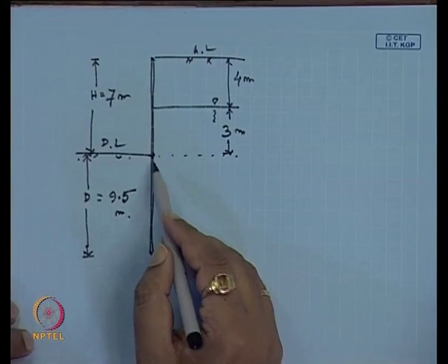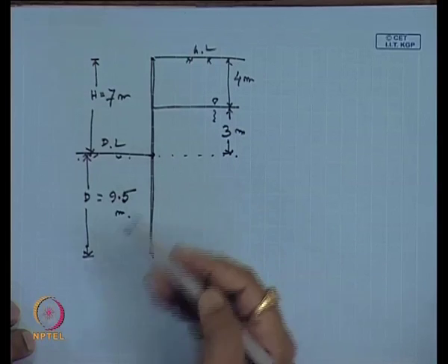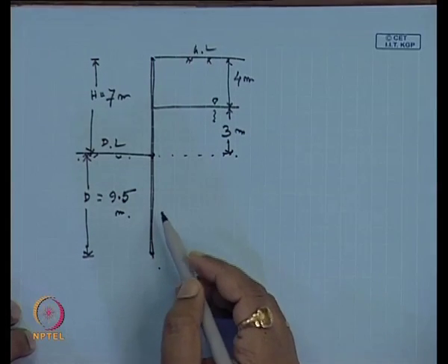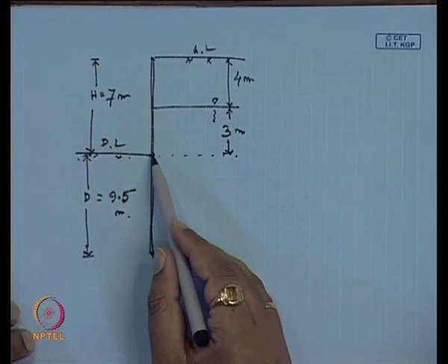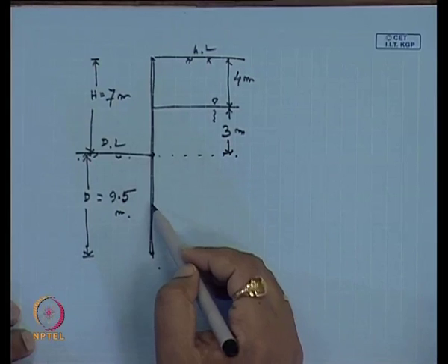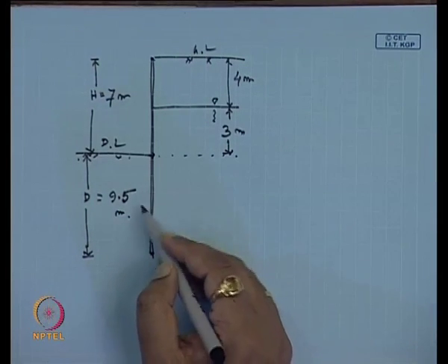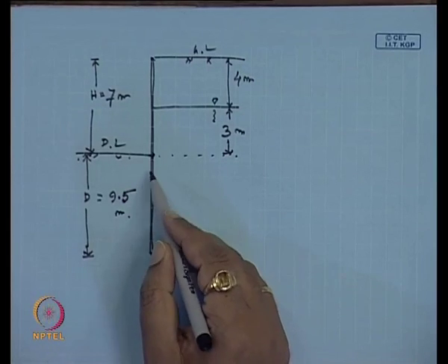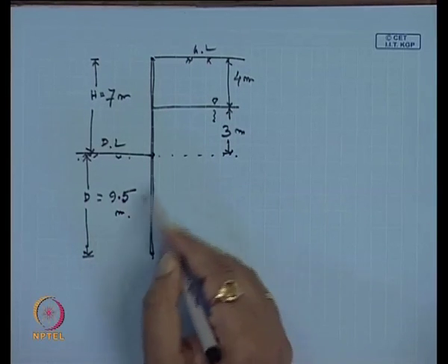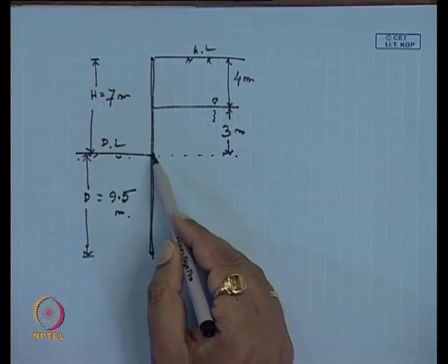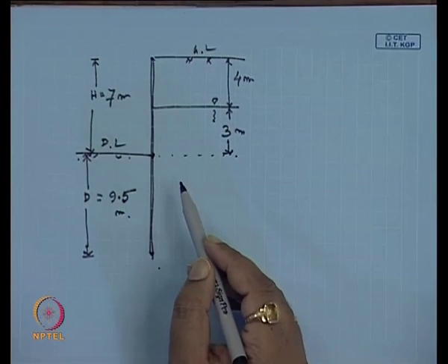One thing is that we have to go for a very high depth for this type of flexible structure. In the next section I will discuss how to design the anchored sheet pile, because sometimes this required depth is very high. All the resistance is coming from the depth of the sheet pile, from the soil, so providing this higher depth is sometimes very difficult.